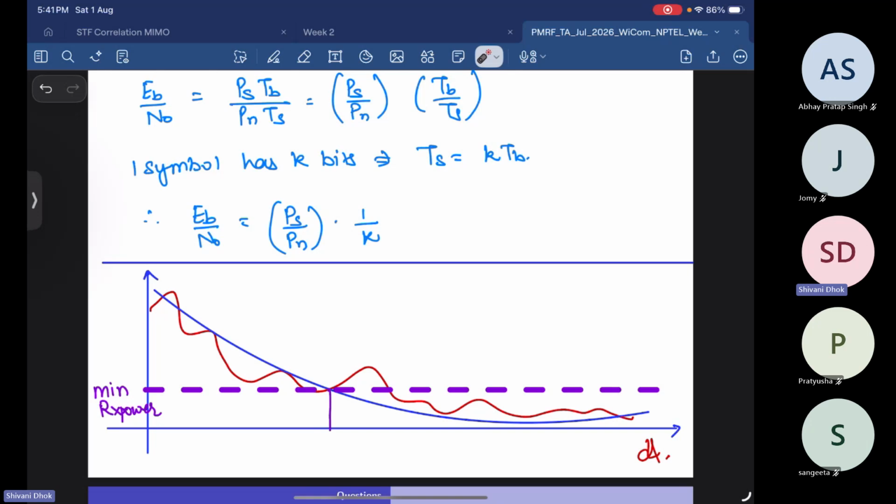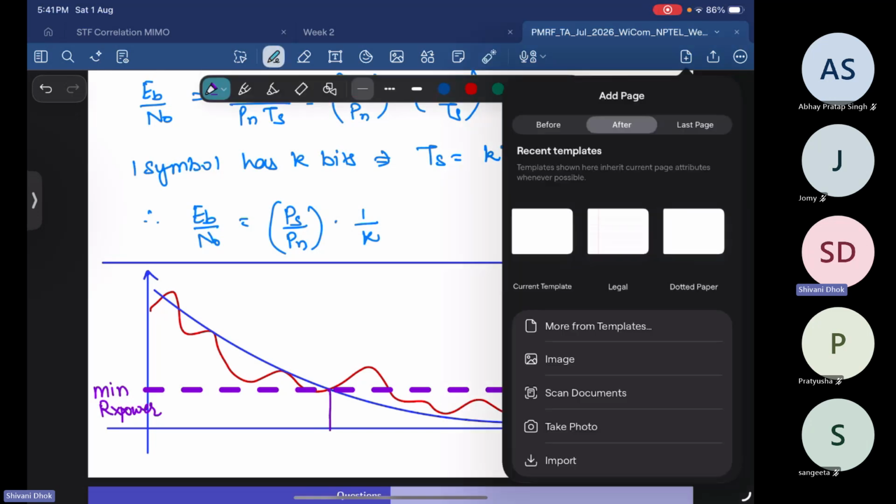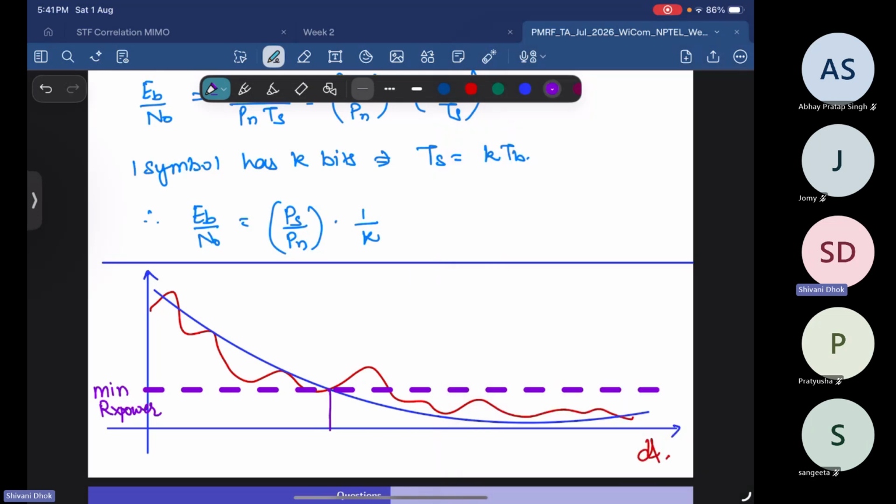This is outage. Now, since your signal is a random quantity, at a given time instant you can have different curves of these things. So instead of having a standard notion of outage, like after a particular span, you don't know exactly how you're going to receive. Your noise is also random. So instead of understanding outage, you say something known as probability of outage.